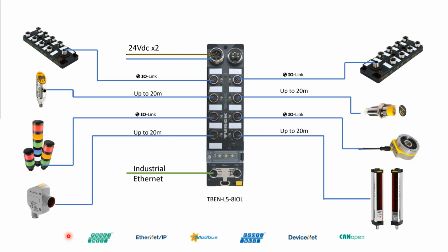So with IO-Link, and back at our slide here, now I've got my analog, pressure or temperature transmitter. I've got my distance laser sensor giving me an absolute measurement. This is an easy array, so it's actually giving dimensioning of whatever's passing through, like a box or a log. We got our encoder that we've already kind of talked about. Now we've added indication devices. So now I can get, and if you're looking at the board here, I get a 10-segment TL50 tower light that I can handle with just that 3-wire connection. And so now I'm only taking up 1 port with my indication.